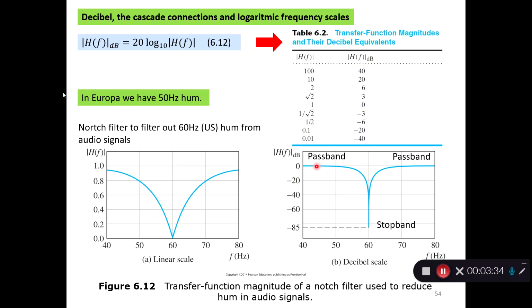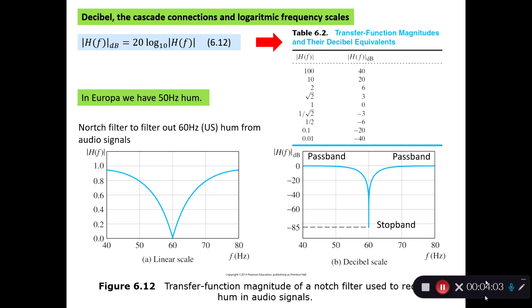The filter lets all these frequencies pass, then one specific frequency is stopped, and then the other frequencies are passed again. The stop band is where we definitely want the filter to attenuate one frequency so much that we can regard it as unimportant to the rest of the data we have. So here it wouldn't matter to get this value into our AD converter.